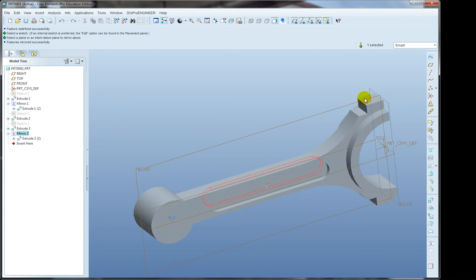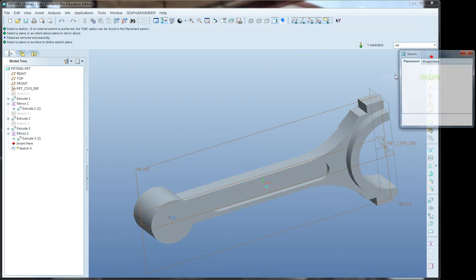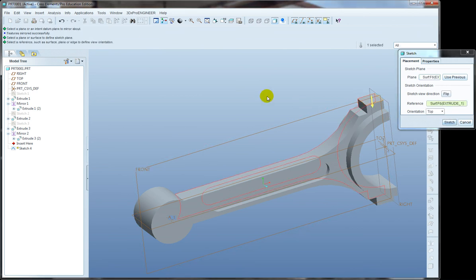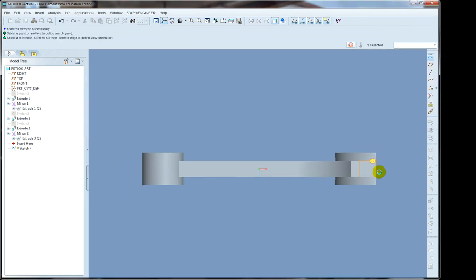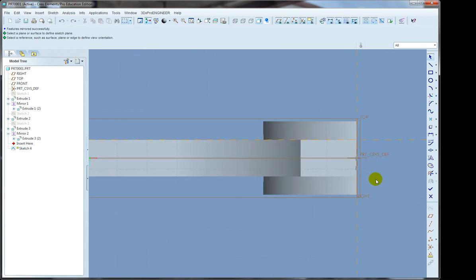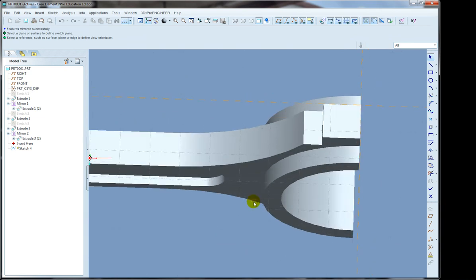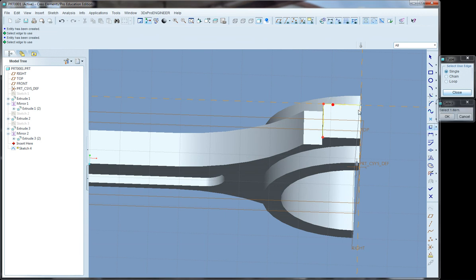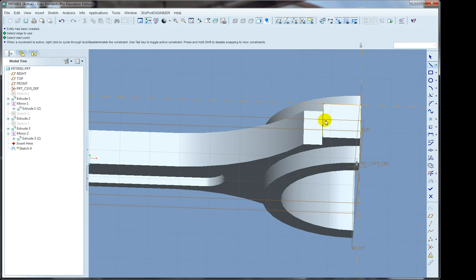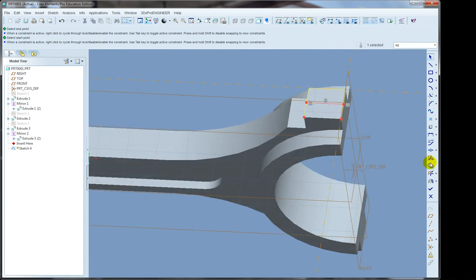So what I'm going to do is a new sketch on this top surface right here, and we'll click Sketch. And this one here, I'm really going to cheat my way through this one, because this can be a lot easier than you might think. I'm just going to go to the Use command, and I'm going to use 3 of these lines. Draw a line that cuts right across. And then I'm going to go to Delete Segments, and delete this and this.